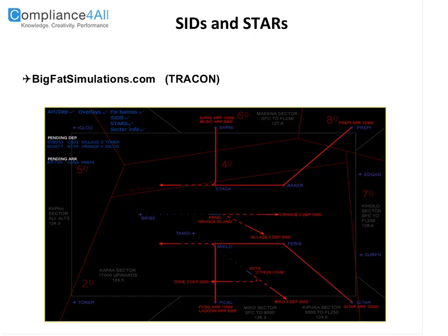These all do the same thing. You can see how the routes are. What this really does is not help the traffic itself, it simply reduces the amount of communications required for every airplane. If he's assigned to this particular STAR, he has a plate that tells him what all these turns are, and he does it. Otherwise, the controller has to tell him to do it or give him radar vectors for all this stuff, which really increases the workload. So this is a workload reducer in the form of reducing the communications burden on the controllers.